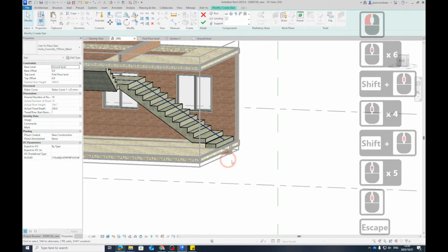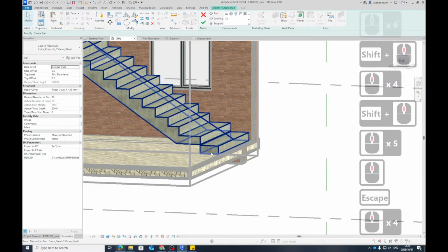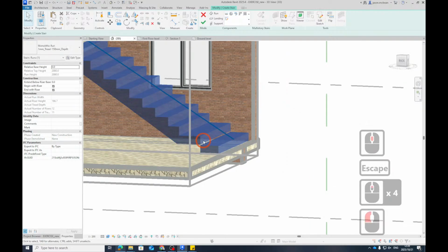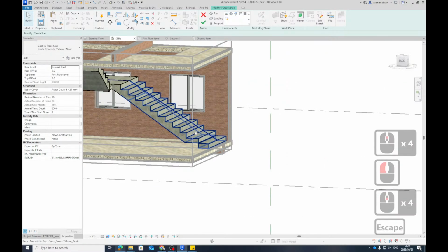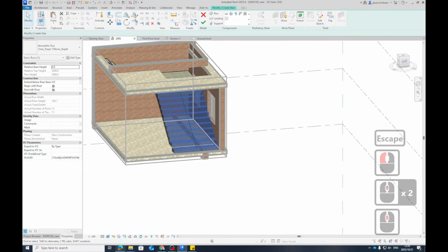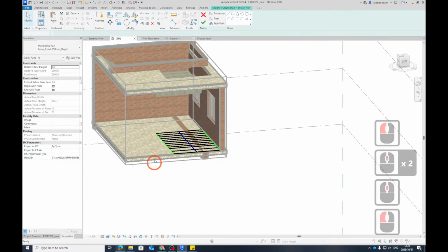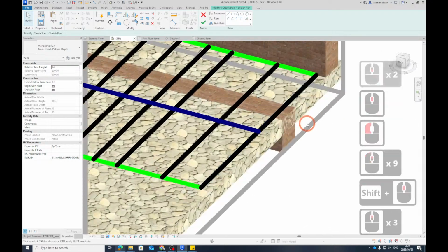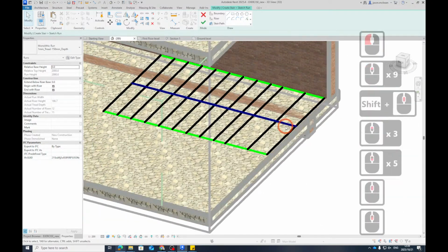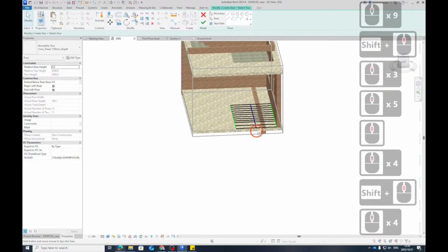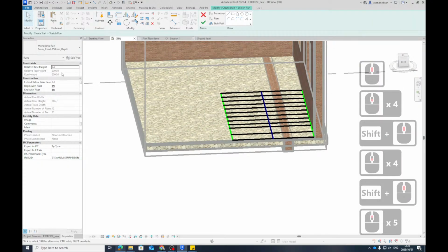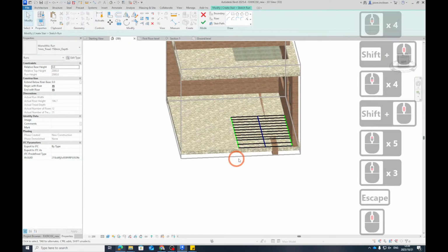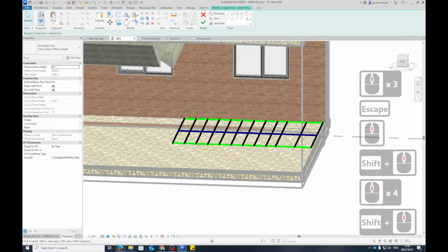But it might mess with the type of stair. Just be careful, it might break it up. But that's fine, you draft over it because Revit is trying to do maths. But provided the steps get longer and shorter, you'll see it will start working, okay? And you just say edit path. I think I know why I did that. This must always be connected and make sure, yeah. So you can make this a monolithic stair, but you make the depth longer. So this will affect the way the stair will work, because now that tread depth will get thicker and thinner.